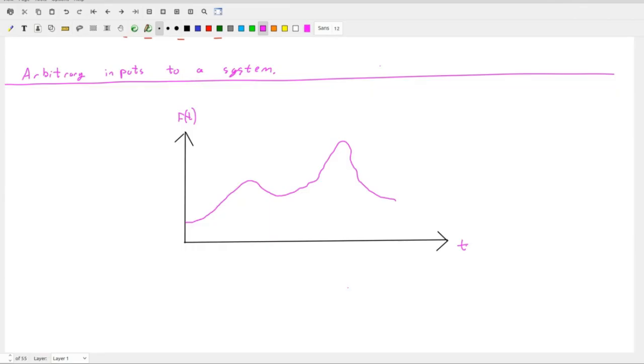The time response of a system to an arbitrary input force in time can be calculated using a series of impulses. This method allows the practitioner to easily solve for the response of any load if you just set all of your impulses into a for loop. This is often more efficient than using direct methods, particularly because you can program it.